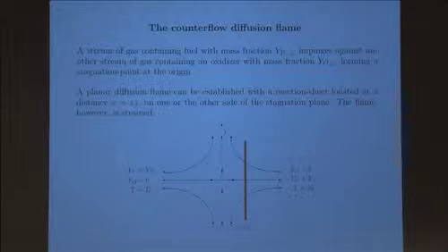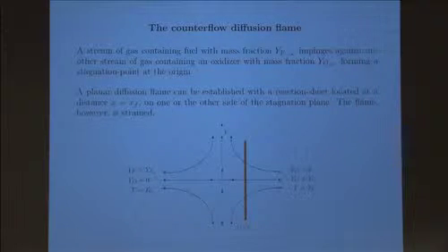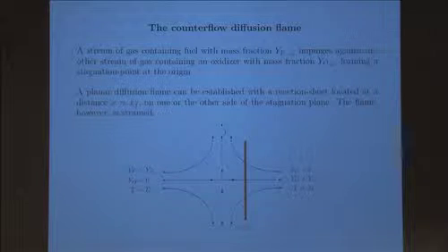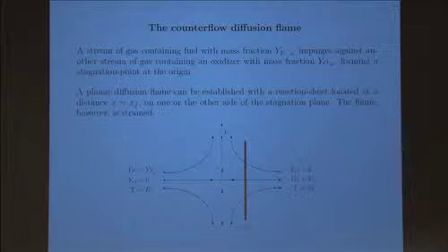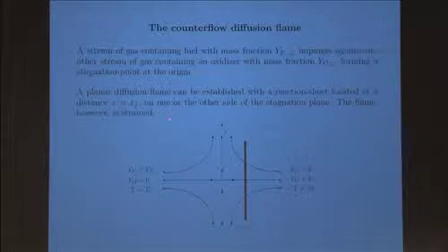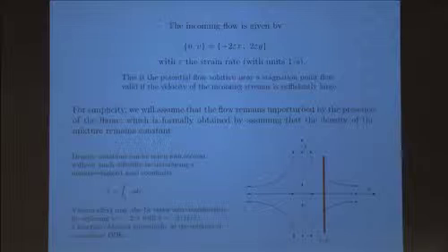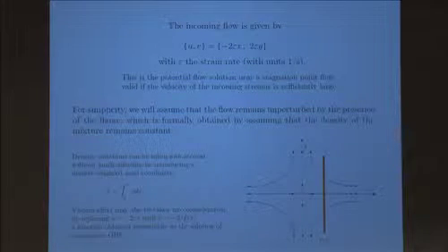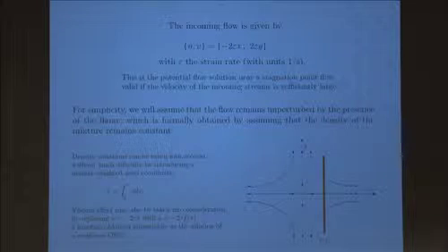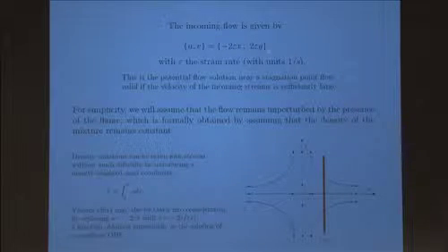Now, in general, the flow field, of course, varies as the temperature increases, the density changes, and so there is an effect on the flow field, but we are going to assume, similar to Burke and Schumann and similar to other ideas that I presented before, that the flow field is not very much affected by the variation in temperature and density, and so we're going to assume a constant density. In this case, the flow field is very simple because that's the flow field of a stagnation point flow. In fact, it's the flow where viscosity has also been neglected. That's an ideal gas or potential flow.